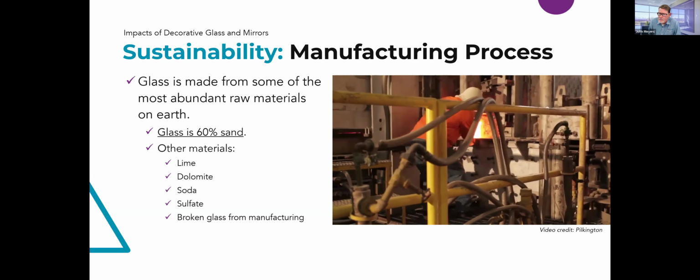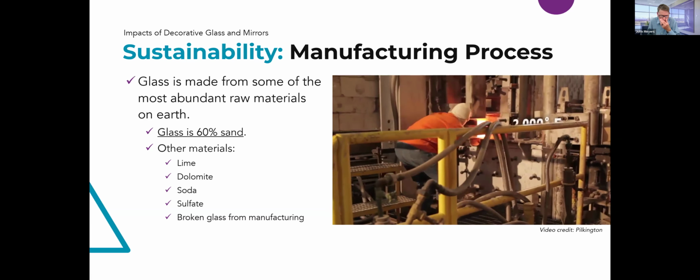The glass leaves the conditioning end of the melting zone at a temperature of 2000 degrees Fahrenheit through a narrow canal where it passes to the heart of the process, the tin bath. Molten glass enters the tin bath and floats on top of the more dense molten tin, like oil floating on water. Here, the glass spreads out, following the perfect flatness of the tin, so that the upper and lower surfaces of the glass remain absolutely flat and parallel with perfect spectral properties.